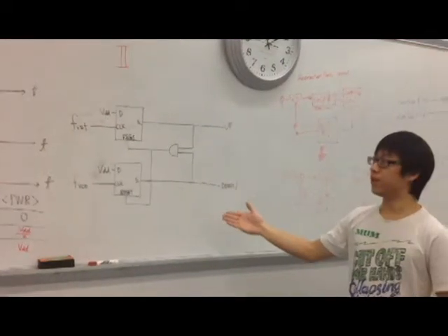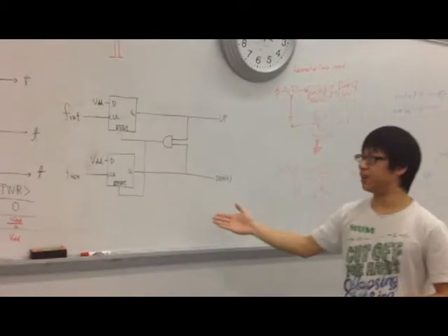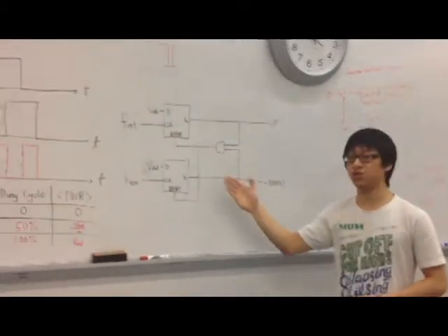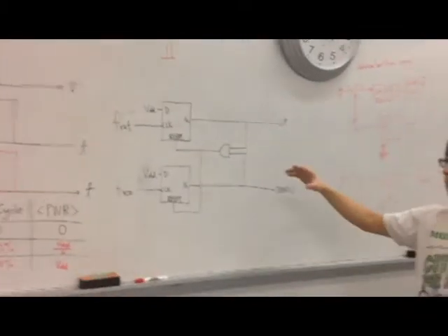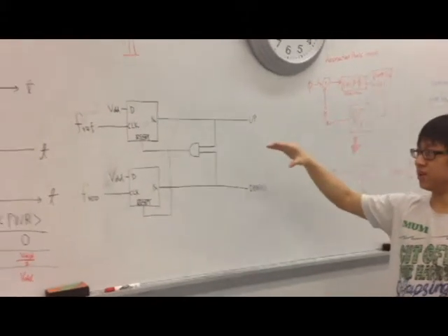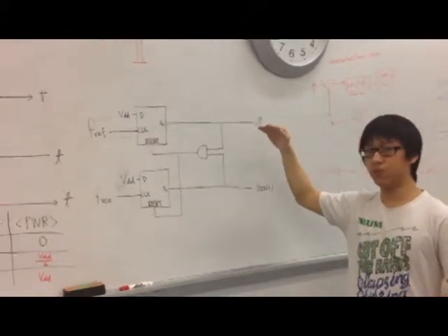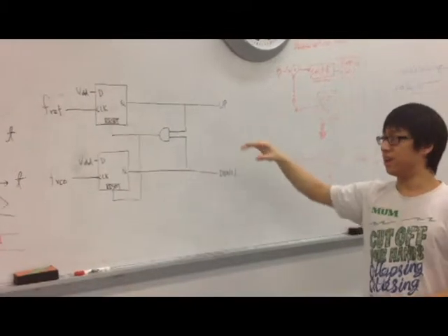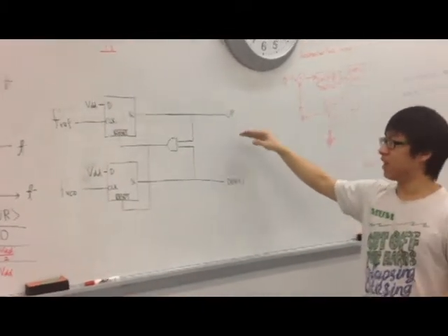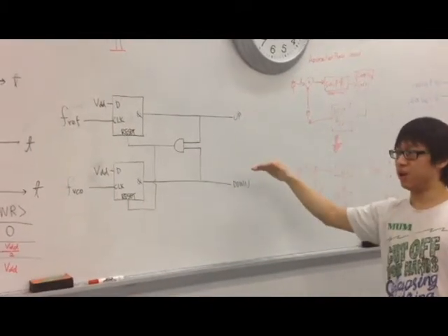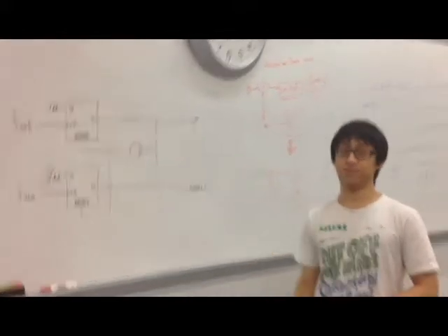The second way we can implement the phase detector digitally is through two positive edge triggered D flip-flops. This setup allows the system to detect which signal is leading the other and results in the speeding up or slowing down of the VCO signal.